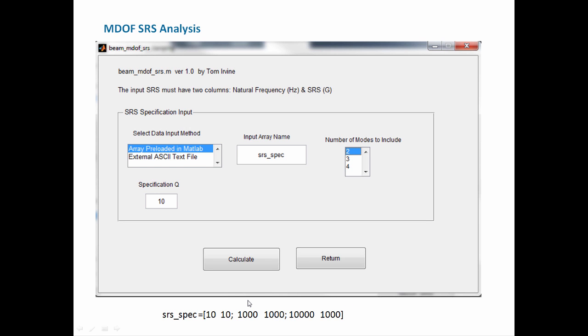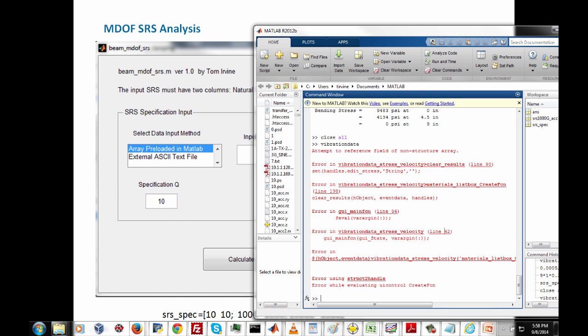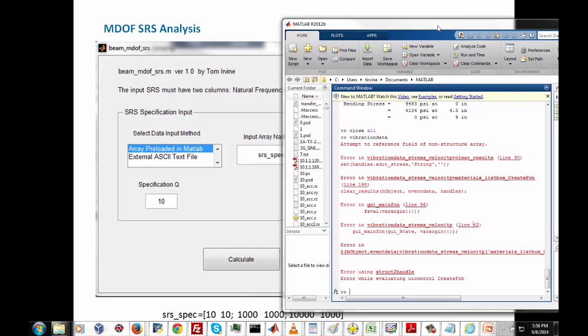So this is just taking our natural frequencies from our normal modes analysis, and not even doing modal transient, but just taking the SRS and picking off responses from the SRS from our handful of modal natural frequencies, and then calculating the equivalent pseudo velocities and accounting for the participation factors, and then calculating resulting pseudo velocities, and then on to stress that way. So this is the really quick and simple method.